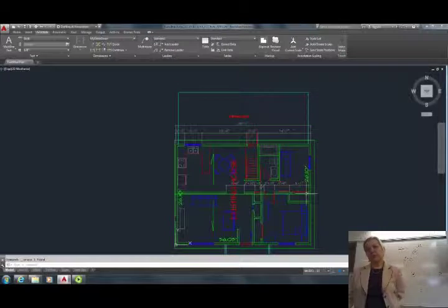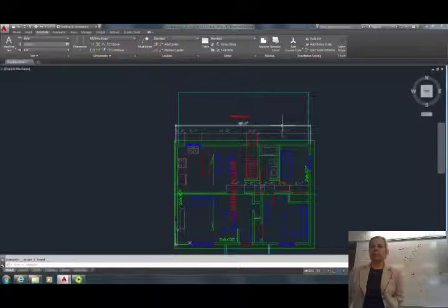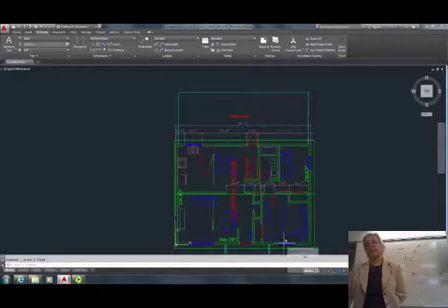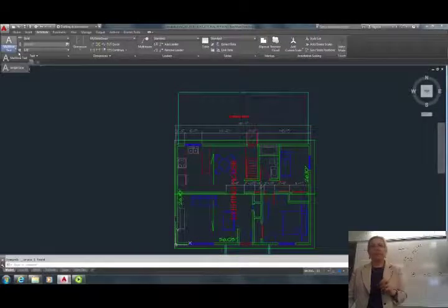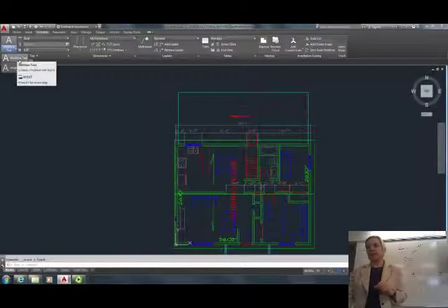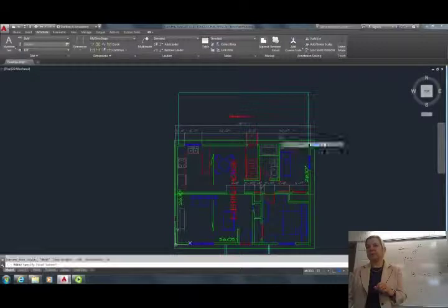The same goes for vertical strings. You don't have to repeat overall dimensions on all sides, so one overall dimension in both directions is enough. If you have the landscaping stuff, clearances, then they also should be dimensioned. So let's now talk about the note. Let's say I want to add a simple note, and it's going to be a multi-text note, general note here, sitting in the box,